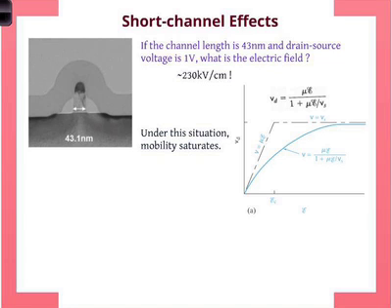So essentially, that's the mobility. This is the drift velocity of the electron. That's the applied electric field. This is the linear region where the field is small, this is the region where the field is large, and this is the intermediate region. In almost all cases, you are either in the intermediate region or the high field region, which means you have to account for an equation where the drift velocity is dependent upon the electric field. Of course, when the field is very high, it just saturates to a Vs, as shown here.